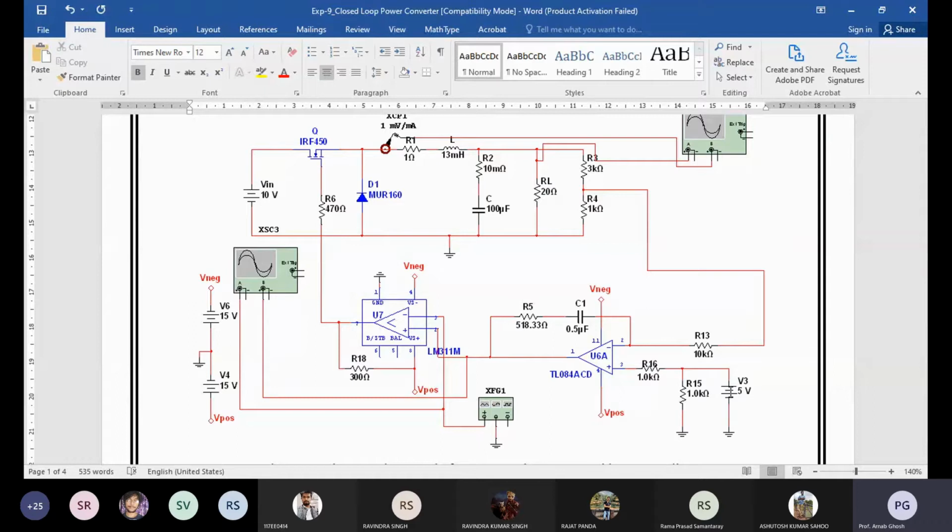Okay, if your reference value is 5 and the output you get over there is 0.1 volt, definitely it should not be comparable. So you have to scale down that value. Okay, so that voltage value, in case of tacho generator, will be less, so you have to scale it down up to your reference voltage value. That reference voltage value should be the equivalent voltage value of your equivalent motor speed.